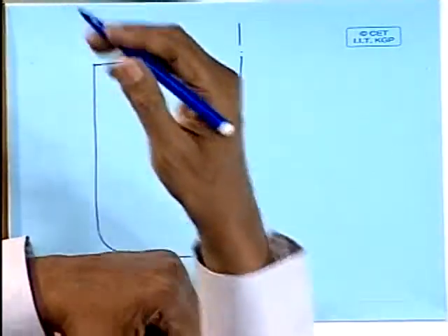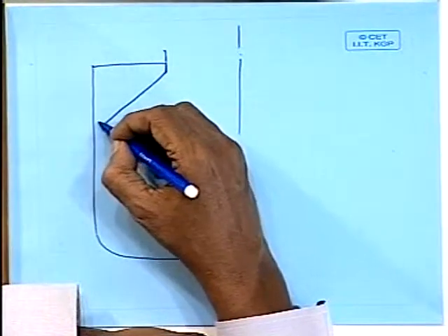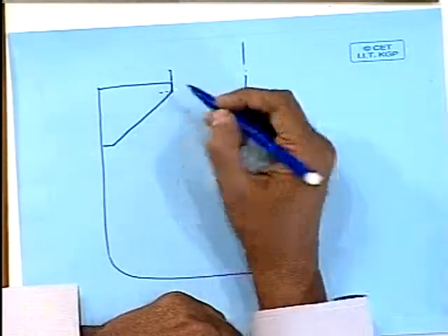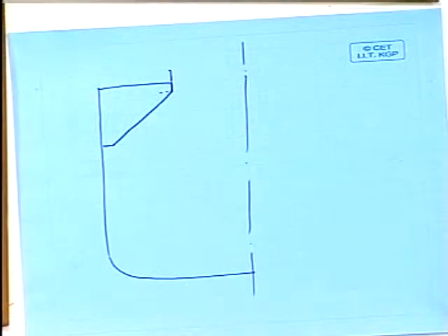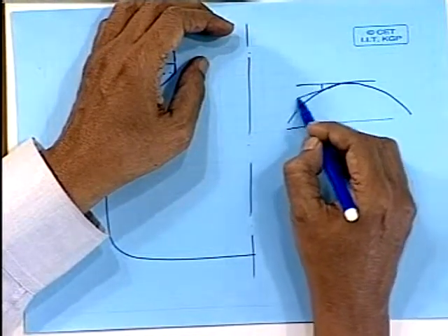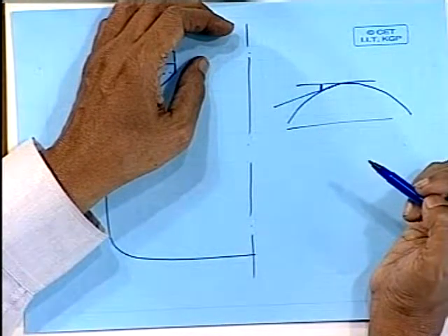What is the angle of this? This is what you had asked. The angle of this side tank, how much should it be to the horizontal? We had said that it should be more than the angle of repose. You asked about angle of repose, no, Mr. Mukherjee? Yes. Angle of repose is the angle that the top surface makes with the horizontal when you dump a bulk cargo. This is called angle of repose.